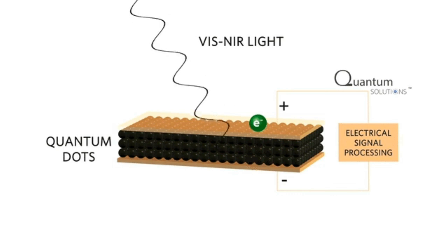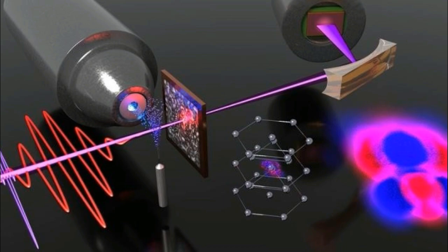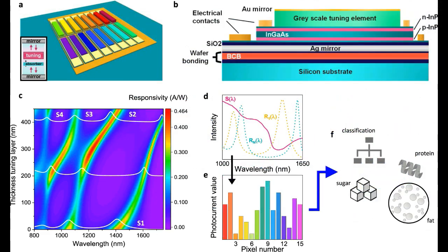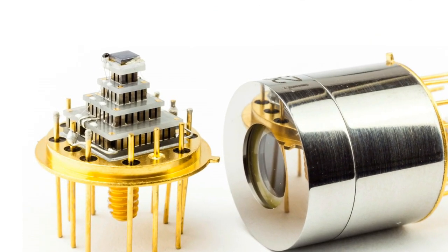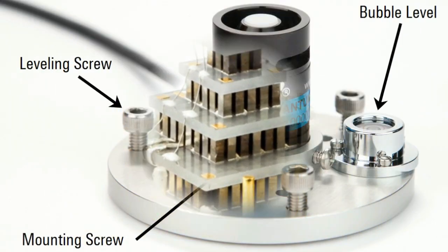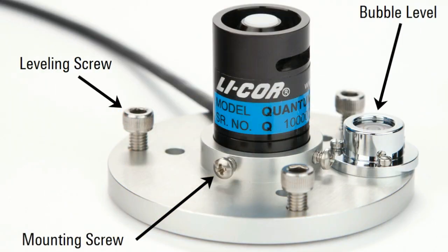Compared to thermal IR sensors, quantum sensors detect photons and are much more sensitive than sensing heat. Quantum infrared sensors represent the cutting edge of IR sensor technology. They are wavelength dependent and known for their quick response times and high detection accuracy. They require periodic cooling to ensure precise measurements, making their operation slightly more complex than thermal sensors.